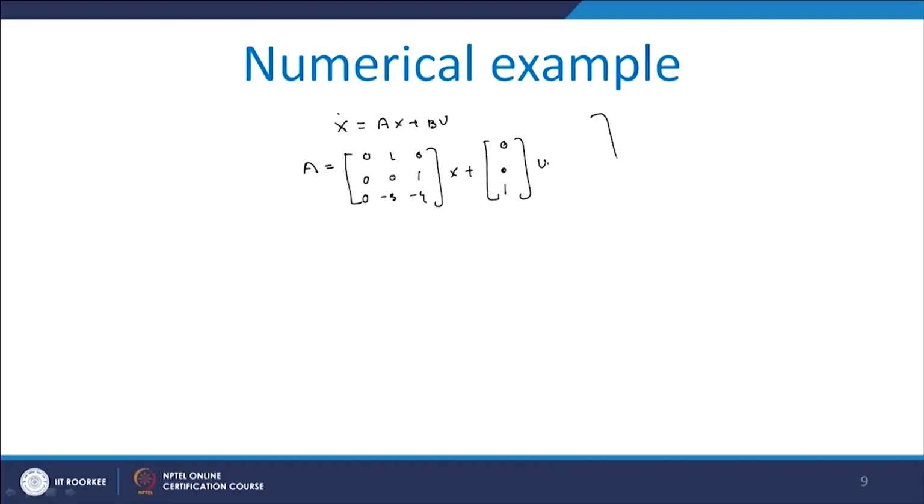and our desired poles are at -2, -1 plus minus j1. These are our desired poles. You will find that in the desired poles we have taken -1 plus minus j1 basically to satisfy the transient issues, and -2 is the real pole.